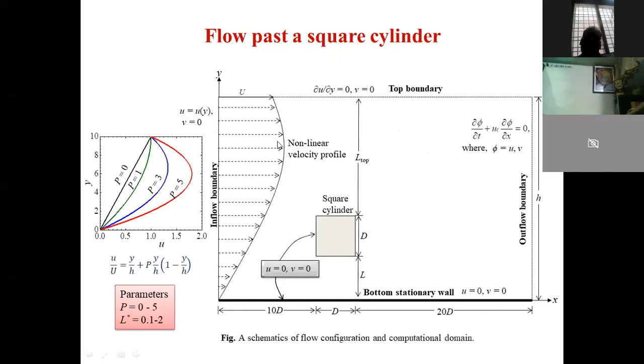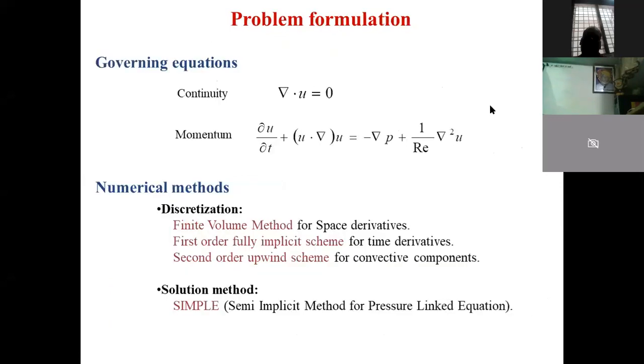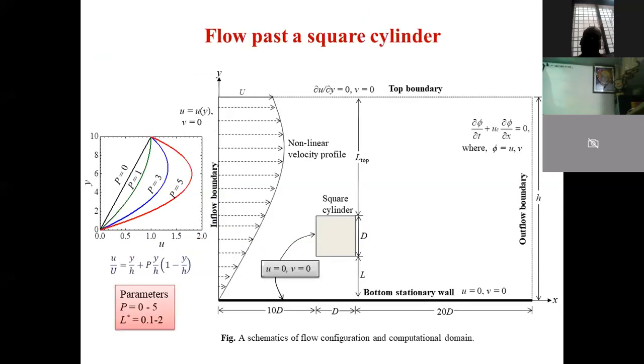But as I said, because we are taking the help of the computer, which doesn't understand these equations, because they are highly non-linear partial differential equations, first we need to convert them into simple algebraic equations so that the computer can understand. That process is called discretization. So what we do here,